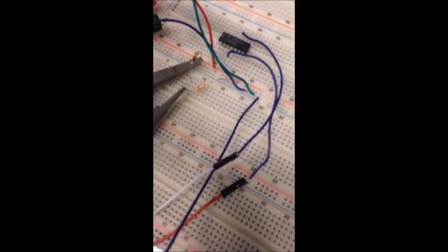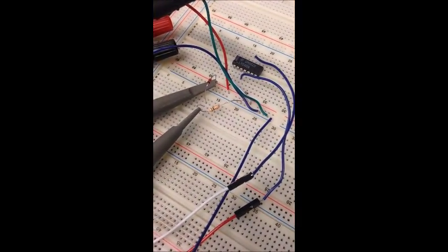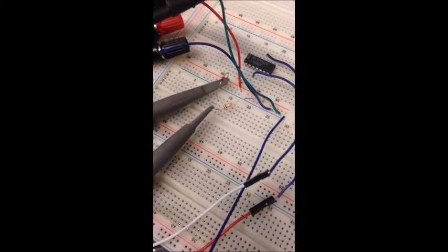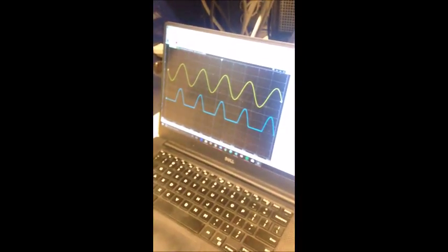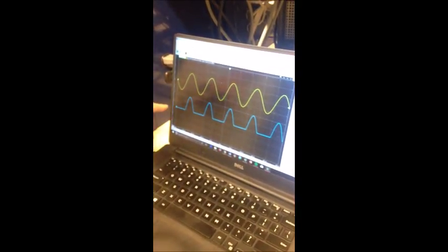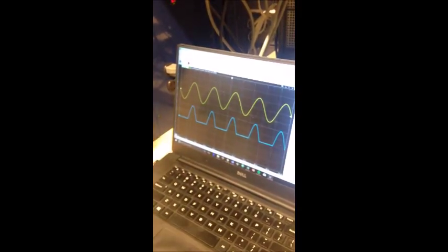So this is part B of the diode lab. It's a half-wave rectifier. Right now the setup is fairly similar to the last one. All you have is your diode, power source, and resistor. But we ran an AC signal in as a source instead of a DC one, and that creates a graph here. It's called a half-wave rectifier because your output voltage will never go negative. That's just the effect of a diode: when the input goes negative, the diode doesn't allow that negative current, so it just flattens out at zero.